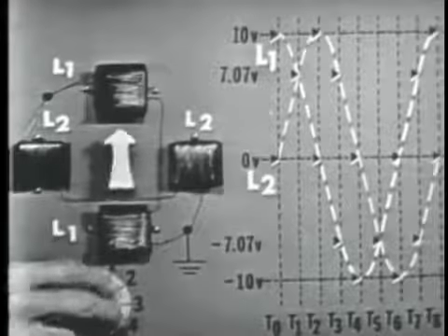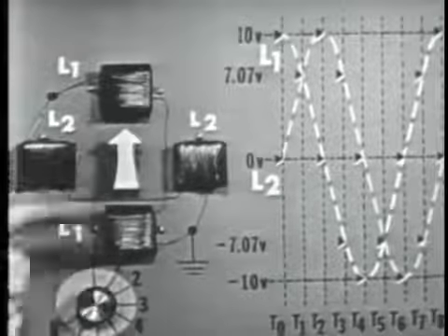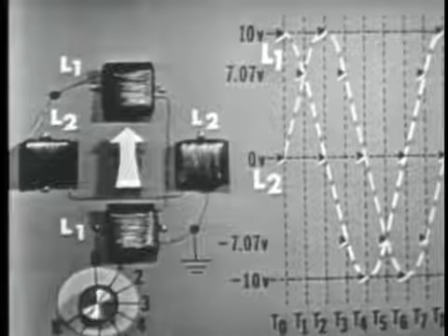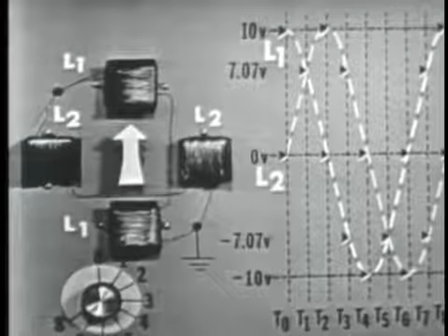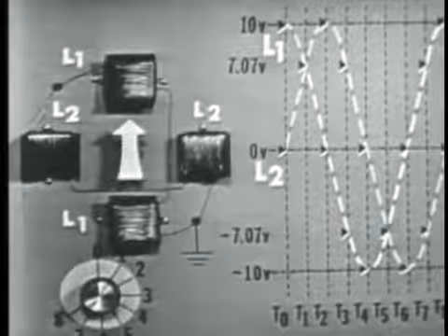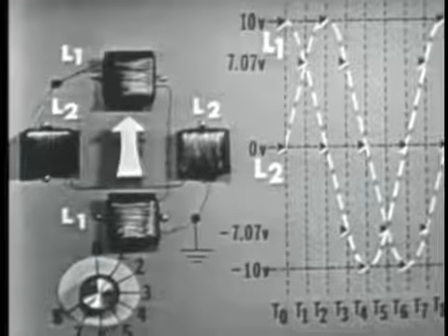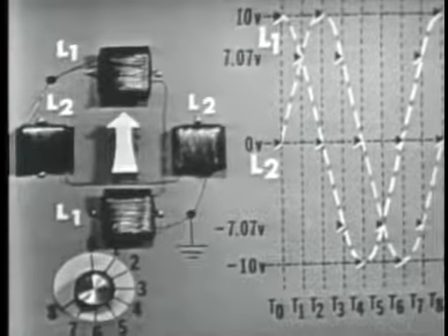By the way, we might point out, Tom, and once again, that you can apply the left-hand rule to all these coils and prove precisely what we've said, right? We can develop a rotating magnetic field. I'm certainly glad you said that. A rotating magnetic field that induces a voltage in the rotor, causing it to become an electromagnet. Right. Which will follow the rotating magnetic field.